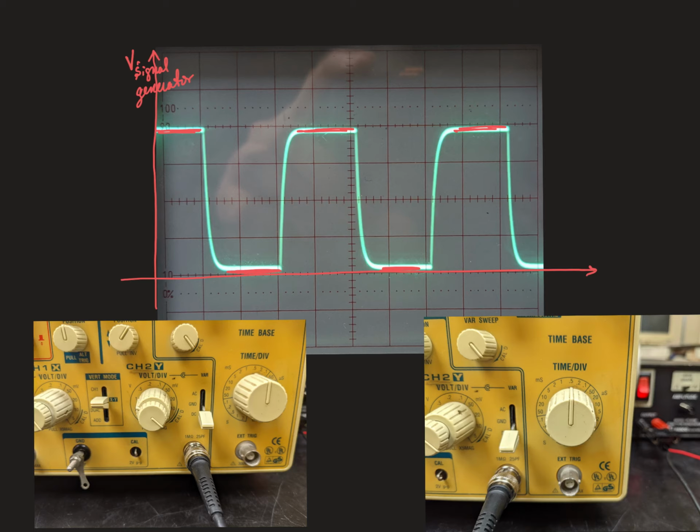That's what we call voltage. The electric potential is the difference between the 2 points that we have. In this case, I'm thinking that this now behaves as a 0, and this is going to be the voltage that it charges. In that case, we can see that the vertical axis is still 1 volt, and I'm referring to the image on the left. It's still 1 volt. Therefore, I can say that this is 1, 2, 3, and it's almost 4, and it happens the same. So that means that that voltage, V sub 0, is approximately 3.8 volts.